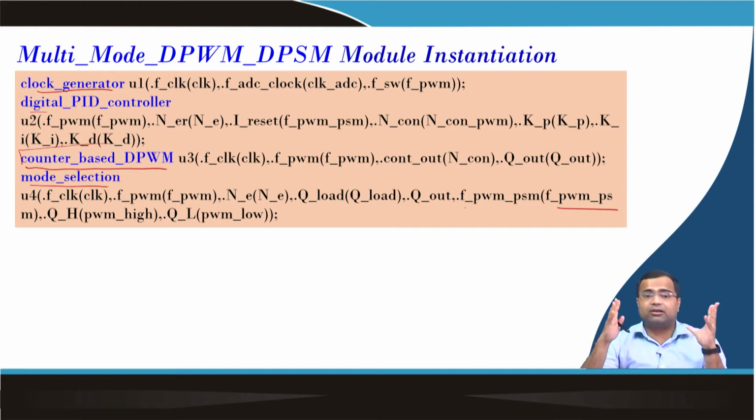There are n number of algorithms, but here we are making it simple just for understanding. We are assuming the load transient command we are sending from our digital control platform by turning on and off the switch resistance, and we know the transient. So, whenever it is a load transient to high load, it moves directly into PWM. When it is going to light load, then we essentially operate the converter under PWM for a few cycles and then move to PSM, and we will explain why we are doing that.